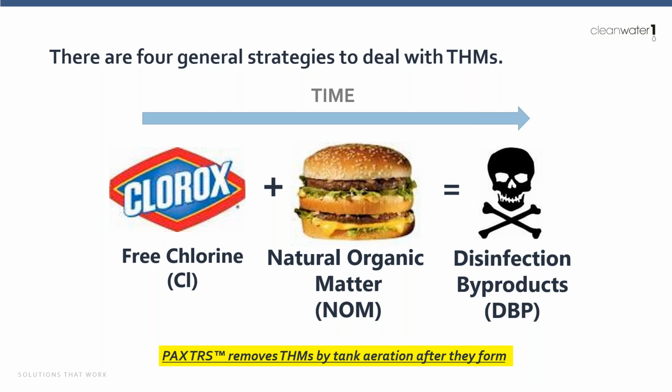Really important, frankly, to point out that from a public health perspective, dealing with the DBPs is a good idea. When we disinfect water with chlorine, we have chlorine molecules interacting with these huge, long natural organic or total organic carbon molecules, these big, long chain molecules. And what's happening is you have the free chlorine atoms. They might snip these molecules into smaller pieces. They're going to attach at various charge locations. And so you end up making a lot of different types of disinfection byproducts.